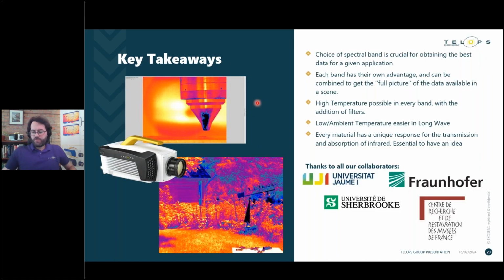So that's it for the webinar. In terms of key takeaways, I want you to remember that each spectral band is crucial for specific applications, and depending on your temperature and your materials, you need to select them carefully because they all have their own advantages. You can combine them when possible to really get a full picture of the data, like the scenes that I was talking about in the last few slides. High temperatures are possible regardless of whether you're in shortwave, midwave, or long wave. You just have to add some filters, and that will affect what you see in the rest of your scene.